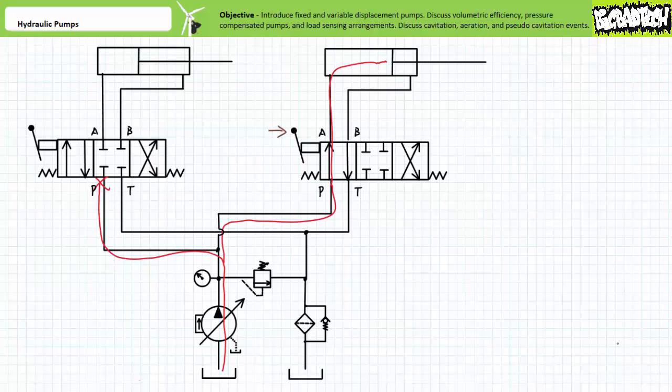When one of the directional control valves shifts position to move an actuator, pressure returns to a load-induced phenomenon and pressure falls to that sufficient to move the load. The pump adjusts displacement to provide flow. When the actuator stalls at the limits of travel, pressure rises to the compensator setting and the pump de-strokes to 0 gallons per minute and the pressure relief valve is not forced to actuate. If leakage occurs while in this position, the pump provides just enough flow to maintain pressure and replace the fluid lost to leakage.